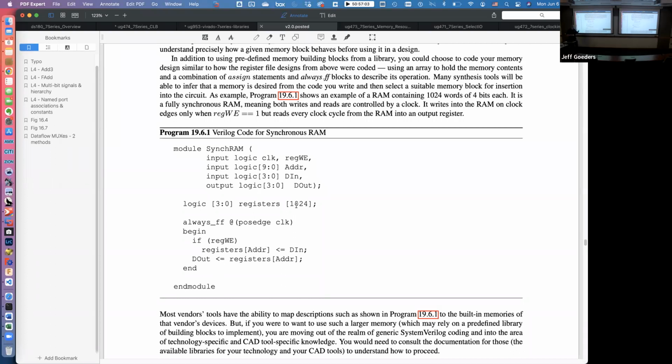I think I will configure this as 1K by 32. And I will just put zeros in for 28 of the data bits, right? Both on read and write, because you're only going to use 4 bits worth. And so the synthesizer will choose that for you. Now, if this had been 1K by, oh, let's say 64. Well, that's too much for one memory.